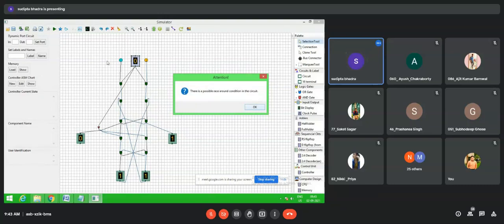Your goal is to design the circuit. In case of a master slave D flip flop, you need 10 NAND gates, and this NOT gate, clock and the input. But here in D flip flop you don't have to give the J and K separately, you give D and then use a NOT gate, and the inverse of D should be input to this another NAND gate. Okay, so you have to design that circuit.